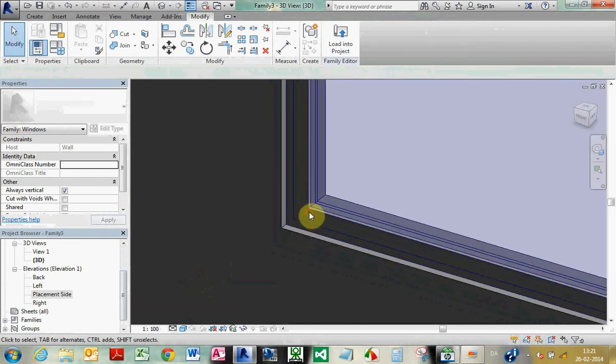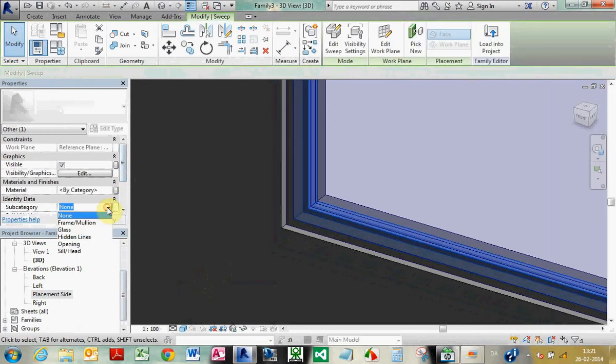if there's a category you use in Revit, then use it, because it's much easier to get family from other people, and you can correct a lot. Well, if you want another color of your glass in your project, you can simply change this Windows subcategory with another material. It will change all the subcategories of Windows, so it's easier to handle if you use those. The frame as well, we can add to the subcategory called frame.